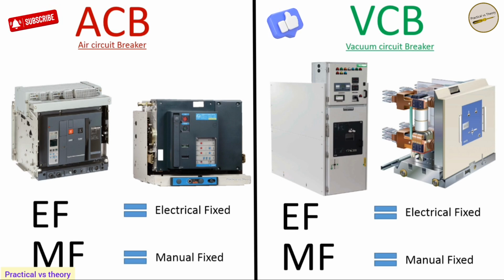After earthing, I can touch it. Okay? For maintenance. Otherwise, don't take any risks because it's a fixed breaker. Look, it costs you less money initially. But the difference is that the maintenance time is longer because you have to take a prior shutdown. You'll have to cut off the entire busbar's supply before you can service the fixed breaker. Because the input poles will have supply. How can you service it?